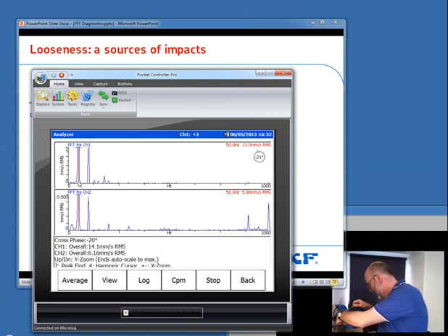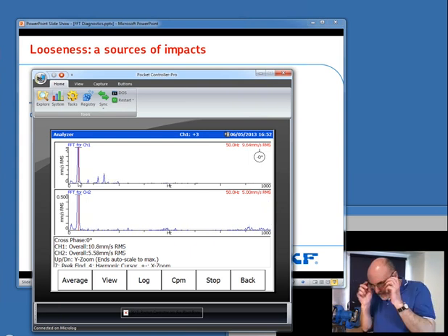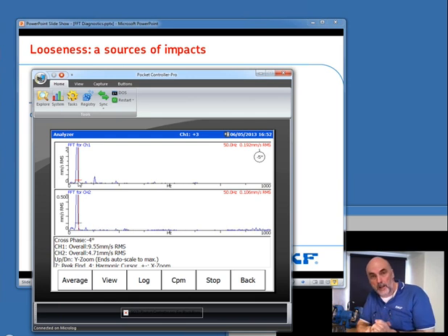So, hopefully, in the almanac, there will be lots and lots of different types of machine fault. I've tried to give you a short view of the common ones. Unbalanced, we're looking for stable readings, high readings. Mechanical looseness, we're looking for lots of harmonics and an increase in the broadband signal. Misalignment, we expect to see a high 2 times, a high 3 times, and we especially want to look at the phase, to look at the relative motion.